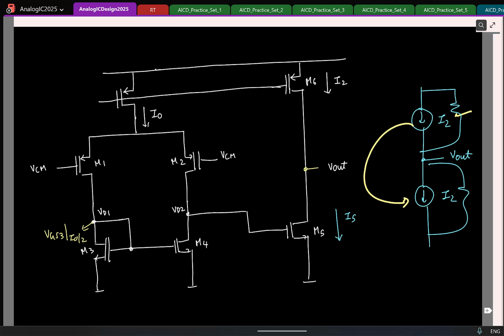One thing I want to clarify is, it is not that all the time this transistor can go out of saturation. If all the stars and planets align, maybe the voltage here drops, but the transistor still remains in saturation to keep the two currents equal. But that's not a great thing, because once again threshold voltage can change with temperature. If threshold voltage changes, this will easily go out of saturation. So this is not the best way to bias it. So what should you do?